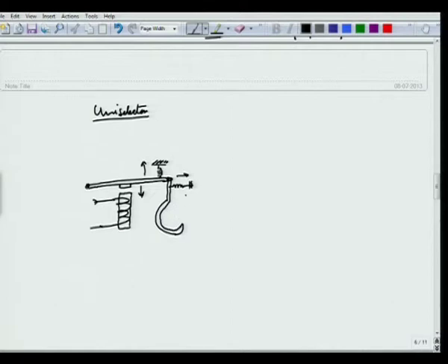As a result, there is a ratchet wheel which is being used on this side. Every time this pulse happens, this wheel moves by one tooth in this particular direction, because when it comes down it will engage with the next tooth because of these two springs, and when it goes back in the return, this wheel is going to rotate.